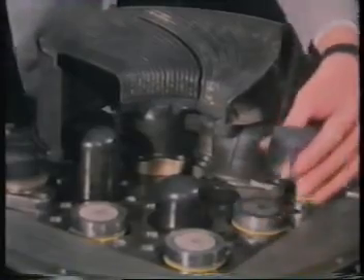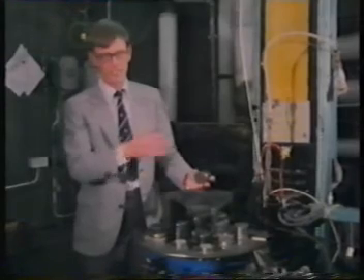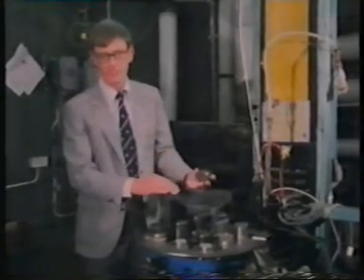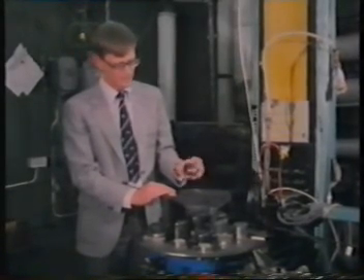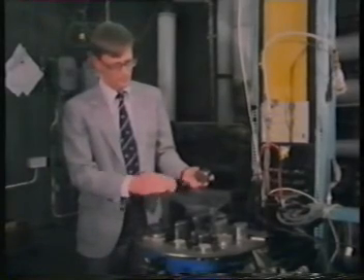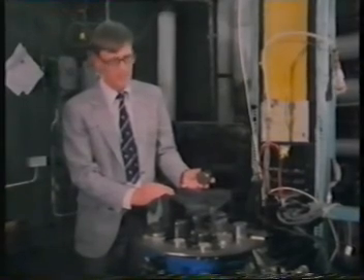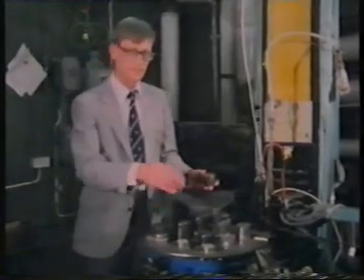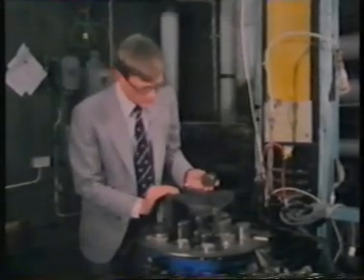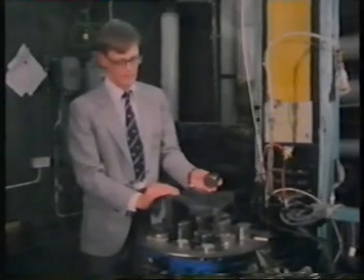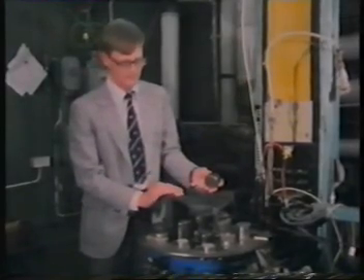And I think the energy that is going out and in the regenerator is about 4 times the heat that is generated in the combustor. So it has a tremendous heat transfer capacity, the regenerator. And if we didn't have the regenerator, of course you could imagine that working fluid at 700 degrees centigrade would enter directly into the cold area, and that would be a tremendous loss, as the efficiency is really dependent on having a small temperature difference between the fluid and the heat exchanger all the time.